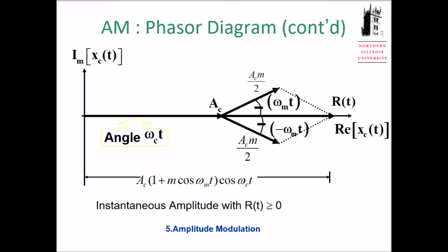So this is another phasor. And then we have three phasors. We call them the carrier, the upper sideband, and the lower sideband. Later we talk about those two in more detail. So add them together, this is my real signal, this is my signal's real part. So we can use phasors to express a sinusoid signal with amplitude, phase angle, and frequency.